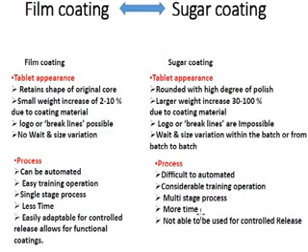But with sugar coating, it is a little bit difficult to automate, because it requires a skilled person, and we have to check from time to time whether it is properly coated on the surface or not. So that's why automatic machines cannot be used for sugar coating, as it requires a skilled person. Actually, it is a multi-stage process compared to film coating. First of all we have to coat your tablet with shellac, and then again we have to go for sub-coating. So there are different stages, and more time is required.